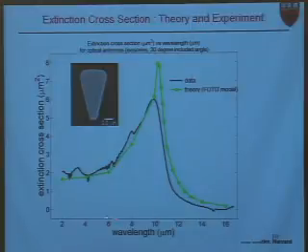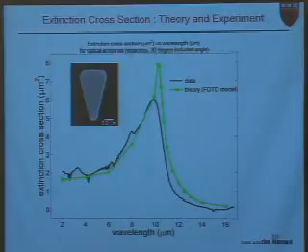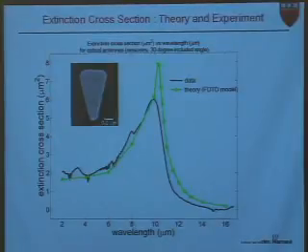And what happens is that at a wavelength of approximately 10 micron, we hit a resonant condition for the antenna. So the currents in the antenna, and also the near fields, that bright spot that I showed on the previous diagram, these are enhanced. And due to the enhanced currents, we also have an enhancement in the scattering, because the antenna radiates, and also in the absorption because of ohmic losses.